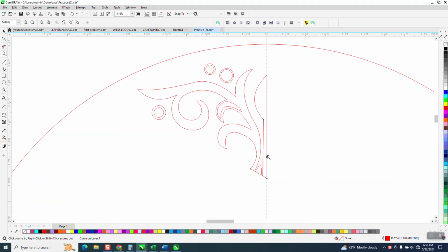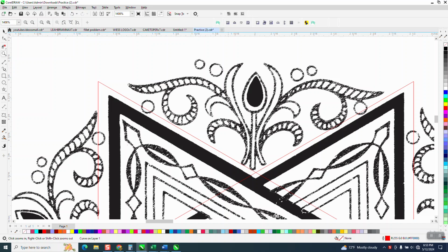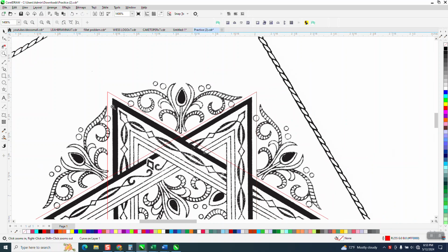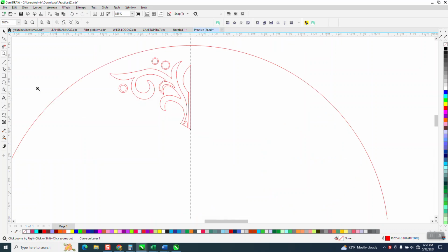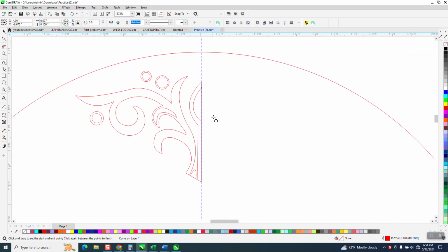I went back to where I started because I thought we want to variegate the leaves of this plant and put in the circle. I'm going to take a 3-point curve line. Let me zoom in here. I'm going to draw that first because that's the easiest. I'm going to go from about right there to about right there. Whoop, not on the line. You want to be on that edge. And then just kind of mimic that circle because we're going to fill that in with black.